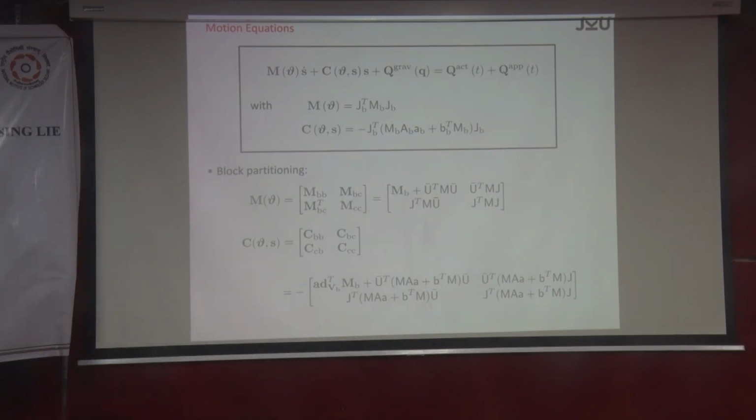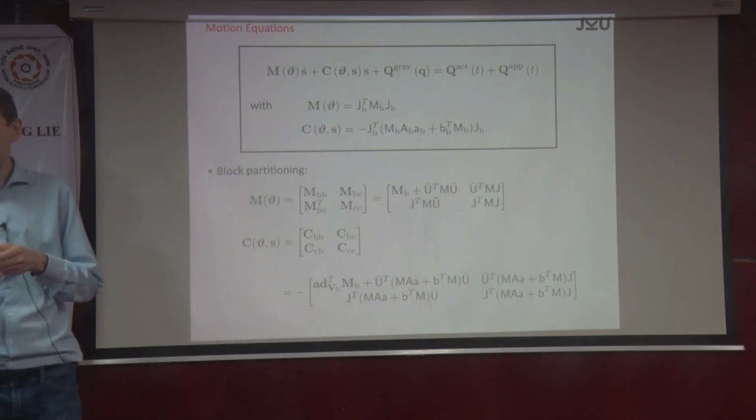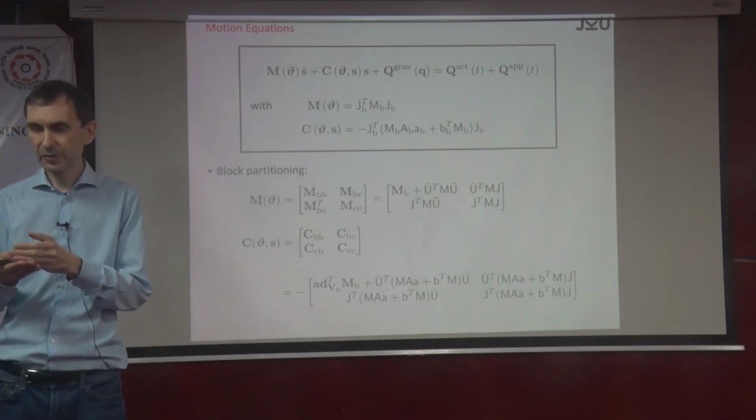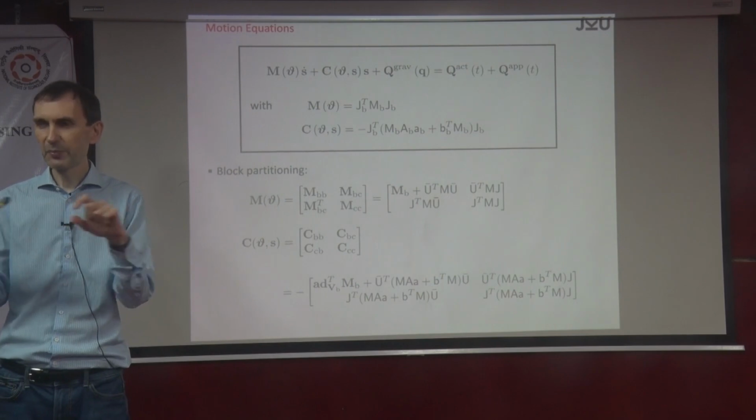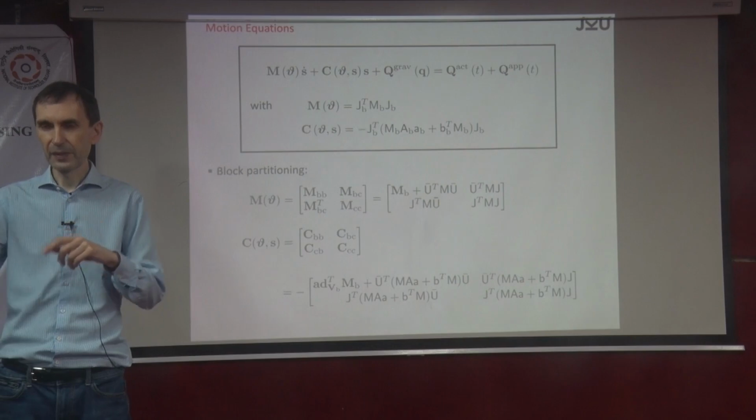And from this you identify the, what's the term in English, the transfer function. Now I have it. And from this you identify a model. Essentially you say we have a mass-spring-damper model for the joint and the links.